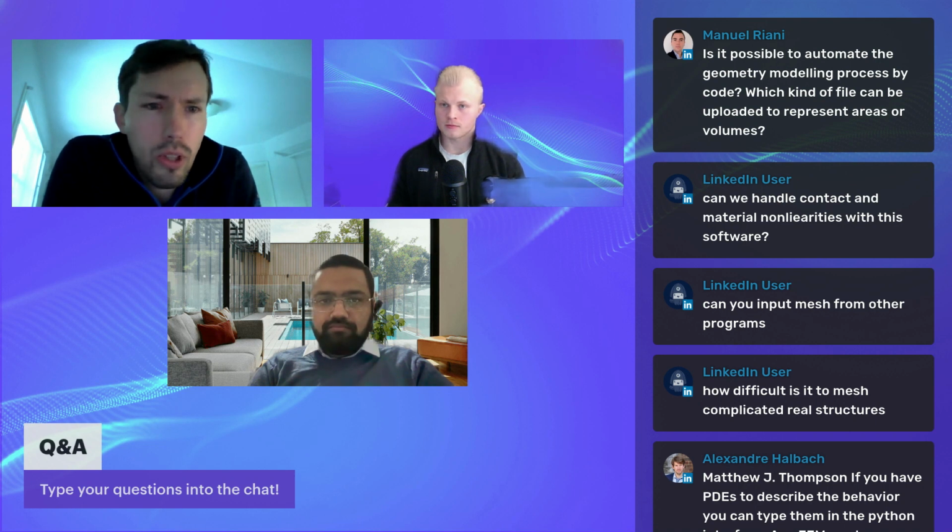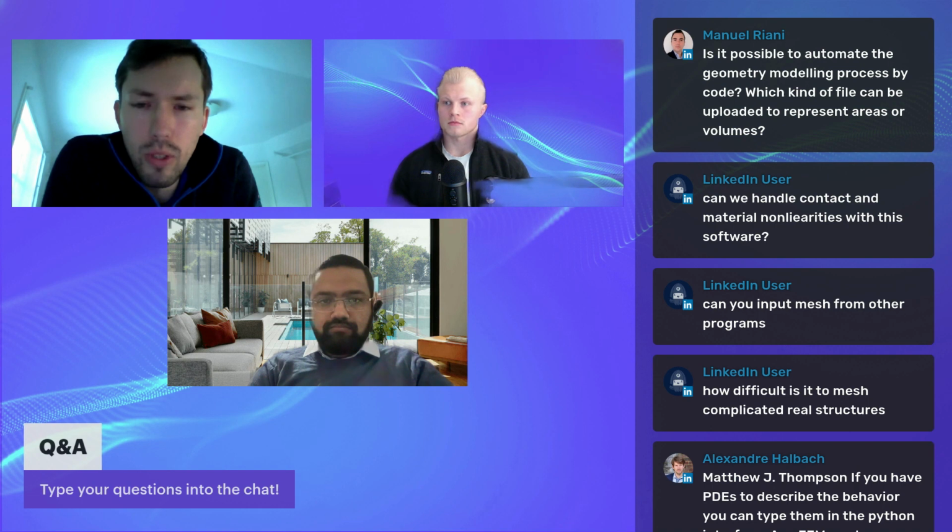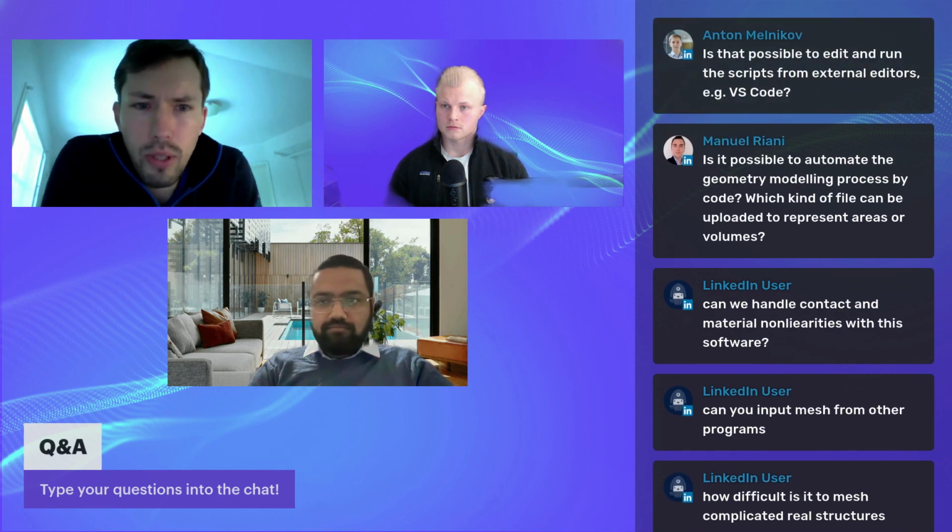What we have not yet explored too much is the material nonlinearity. So we are working with some people who work on plastic deformation. Our solver can handle this, but we're not offering that in the graphical interface right now for sure. And regarding hyperelastic materials, this is also not something we put a lot of focus on, but it is a classical finite element formulation. So that should definitely work easily if you know the equation in the scripting interface.